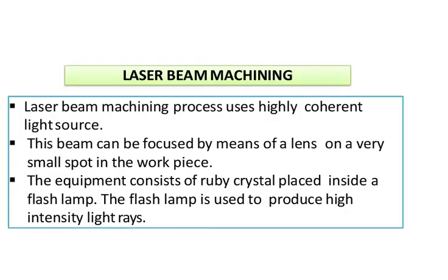So laser beam, we have discussed so many things, isn't it? So laser beam basically is always using a highly coherent light source. And the most important thing is that this beam can be focused by means of a lens on a very small spot on a workpiece also. It doesn't mean that always a big machining or big hole drilling is required for us to go with the laser. But if you want to eject a small spot in the workpiece, then also it can be done with your laser beam.